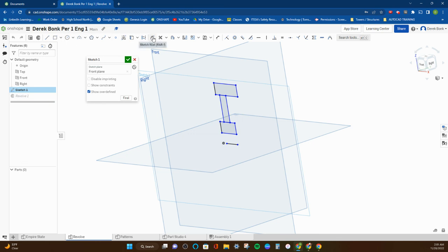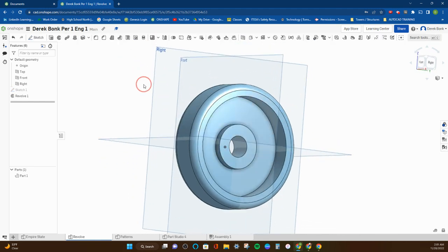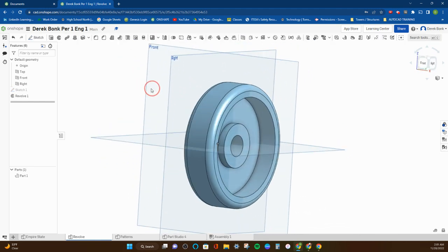There's a round-over type tool called fillet. If I click that, and I click the corner here, based on the size, I'm good with that already. And let me hit this other top corner here. So it already starts to sculpt and round it out and make it look more like a wheel.